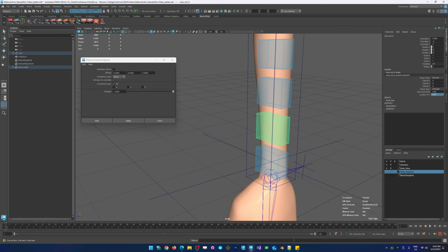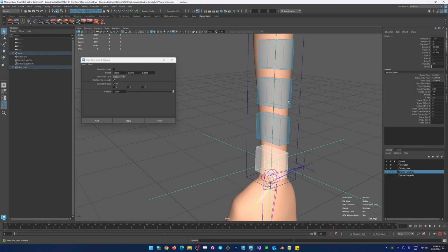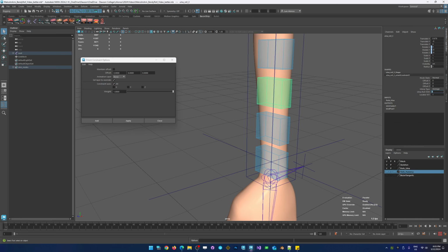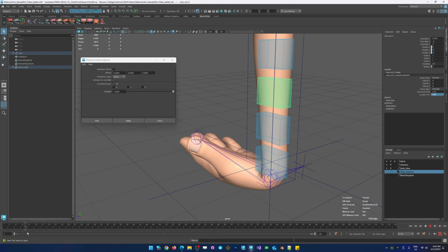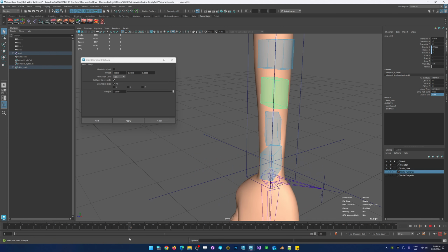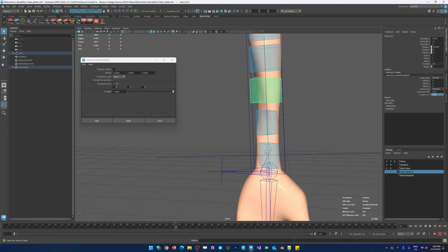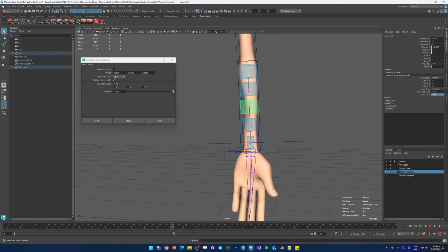And now this one over here is going to have an opposite setup. So I'm going to have these two like so. Still have this here. Apply. If I go here now, I only want 33% of it, and whatever's left goes to the nothing. And now, if you look carefully, you're going to see that it's doing a decent job, considering there's only 3 bones in this setup. We could change it so that the values are a little different. So instead of 0.3, maybe we'll do 0.2, and that's 0.8, and it'll be a little bit softer at the end. And then maybe this guy also would have a little less.